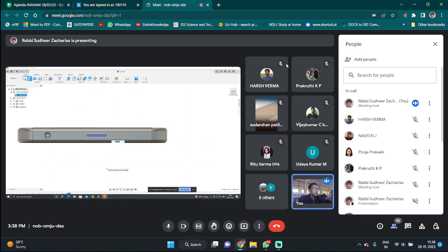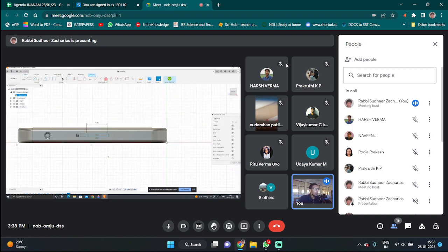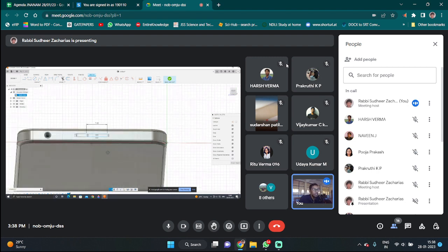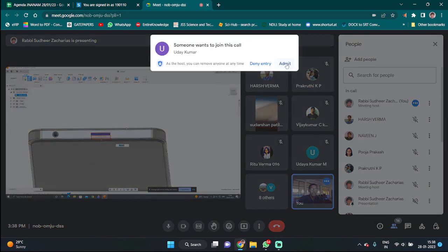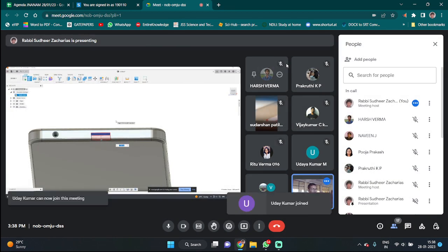You can just use the letter E for extrude. So what are these? These are something called as bind keys. So if we use different keys in a particular fashion, so over here to select multiple edges, I had used Control plus click, right? So that's a bind key. So here the bind key for extrude is the letter E, and then you can click on whatever surface you want to extrude or intrude. Intrude is going on the inside direction, extrude is the outside direction. So for now, let us go inside in this particular case. Okay, enter.